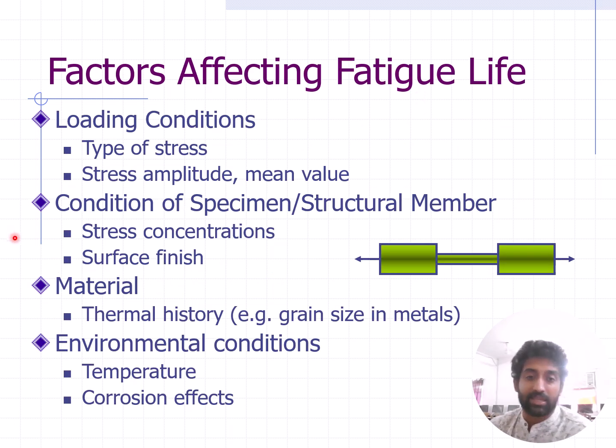Next is our loading conditions: type of load, what is the stress, how the load is given, what is the minimum load, and what approximate maximum load it goes to. Then stress concentration, that means the sharpness and everything where stress concentration may appear, and the surface finish, because surface finish leads to hardness. Hardness affects cracks. If the hardness is maximum, the surface cracks will be fewer, and the chances that the crack will propagate are also less.